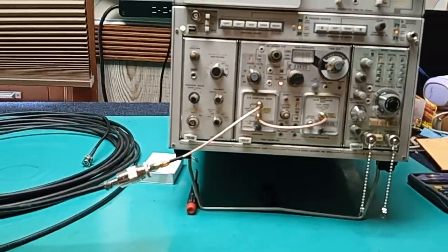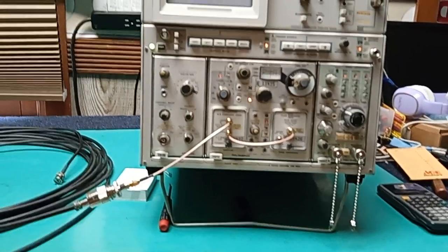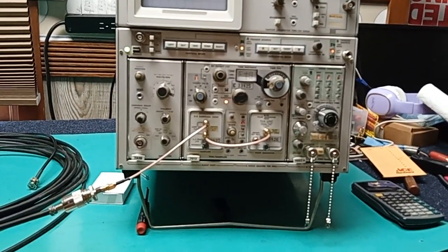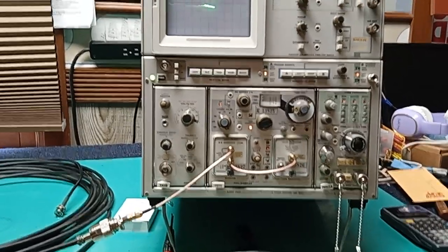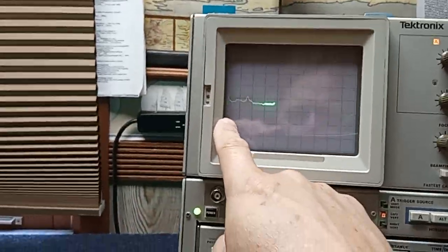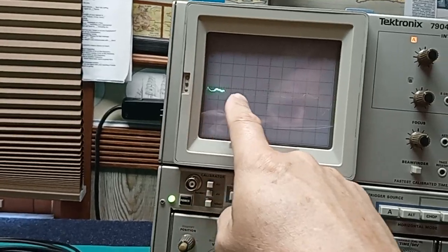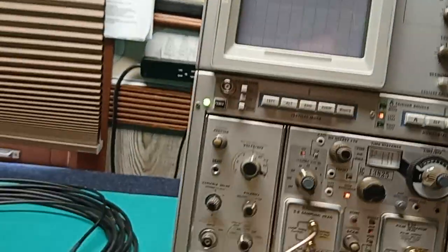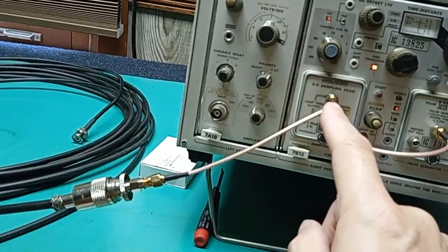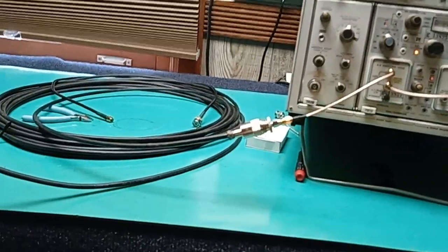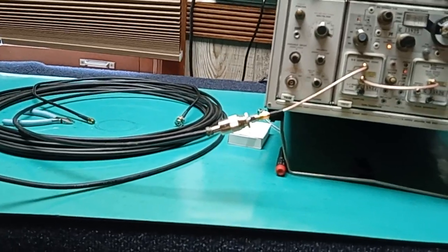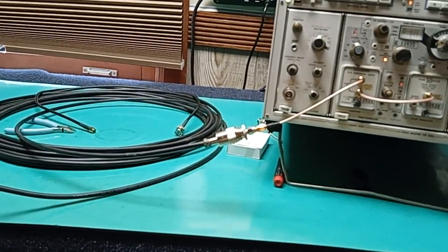There's no such thing as frequency. A TDR does not have a frequency. It is, in a time domain, the inverse of frequency. T equals 1 over F. It is a pulse: start here, and a time to propagate to that fault, which is that physical distance. There is no such thing as impedance of that transmission line. It does not exist in the time domain.